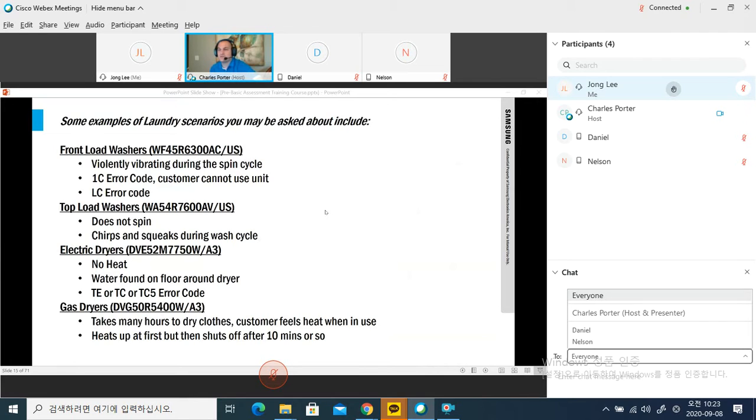The unit will still work. It's just going to shake and vibrate a little bit more than normal in those situations. And if it's in a laundry room up there or a closet, obviously the units can't be moved around. Not a lot you can do about that. So check the floor. A good way to check that is if you can feel it in the floor. Like if you throw this thing on high-speed spin, it gets up to high speed and you can really feel it in your feet. Or you put your hand on the dryer next to it and you can feel the dryer shaking, vibrating, then you know there's something going on with the floor. The floor is just not quite stable.